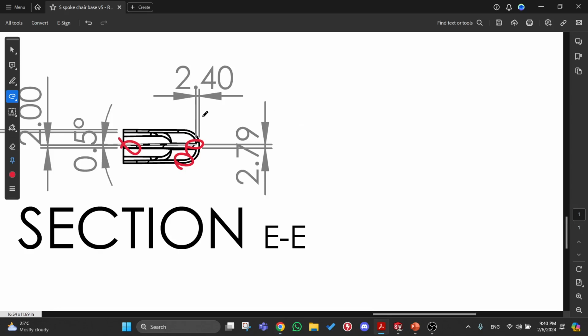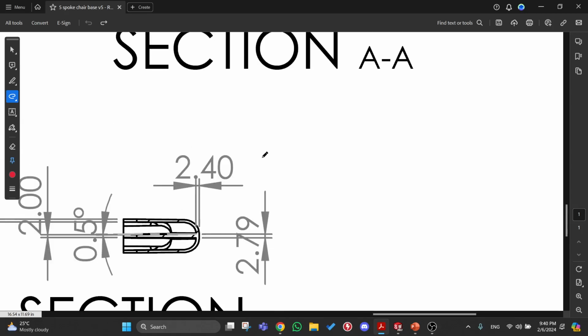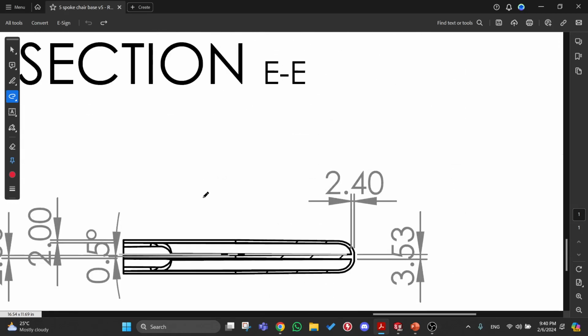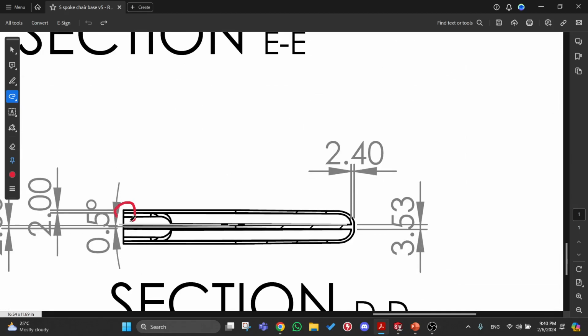And as you can see from this example, my nominal wall thickness is 2.4 millimeters, which is less than 5 mm. However, the issue is 2.79 for rib thickness. Oh no, what will happen? Sink marks. So this is a mistake I made that I forgot to change during my previous module, and hopefully you do not make the same mistake as me. Learn from my mistake and create a better outcome. Another thing I didn't do that well is uniform thickness. This is just 2.4, not really uniform.